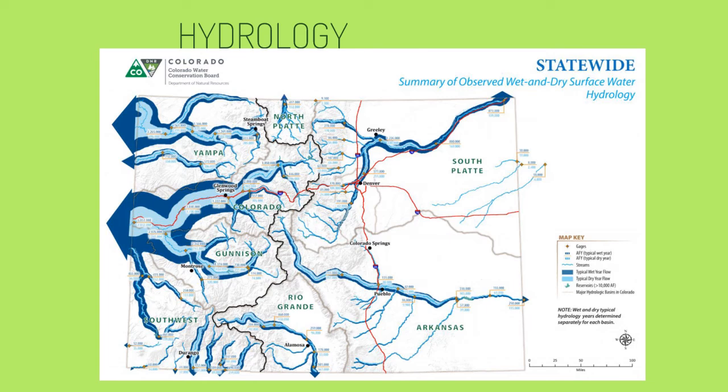In the area where we need to do site grading, we should be able to know where all the water goes. So if our area is prone to accumulation of water, unless this is the intended purpose, we would not want any flooding to happen. So that's where we do site grading to lead water out of the space we want to use.